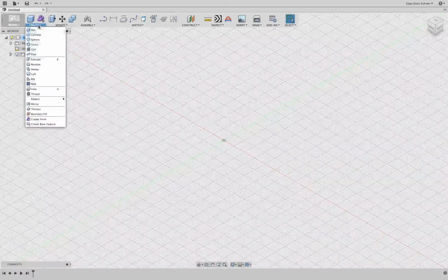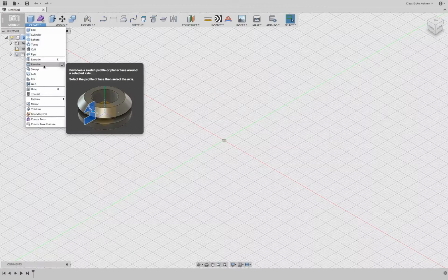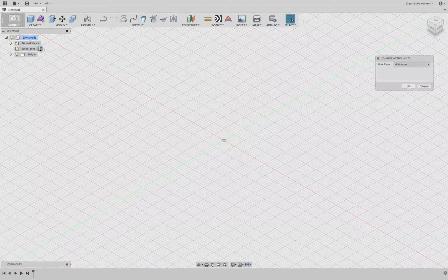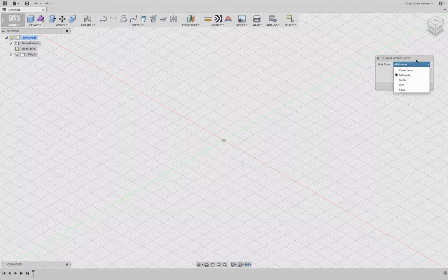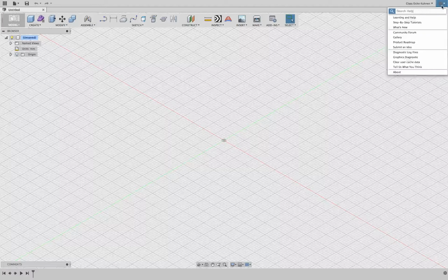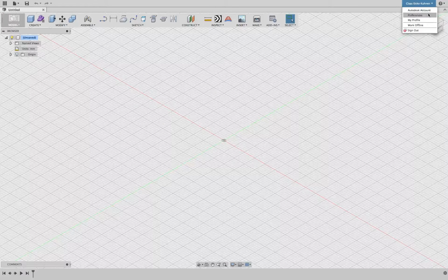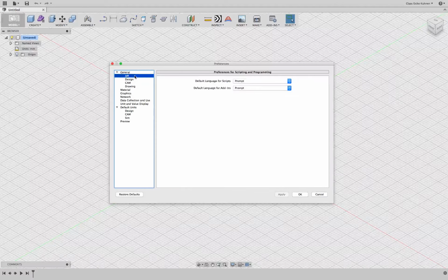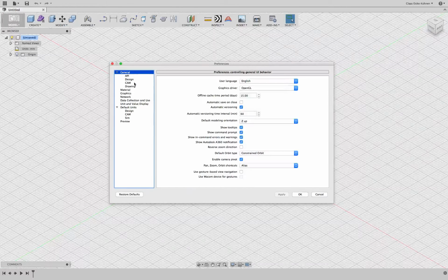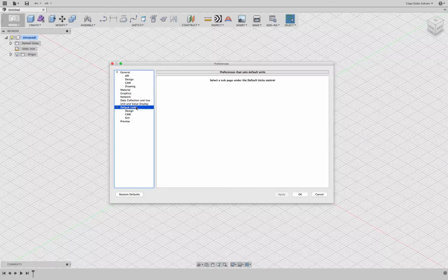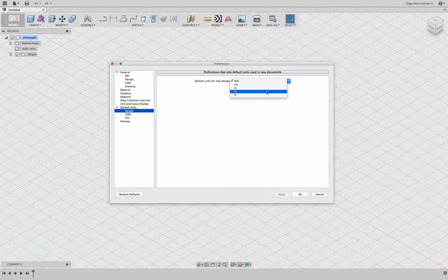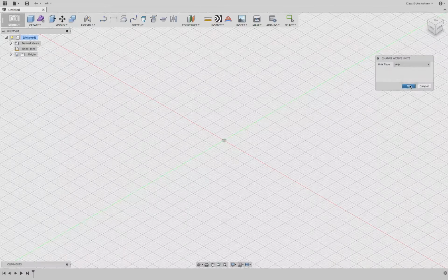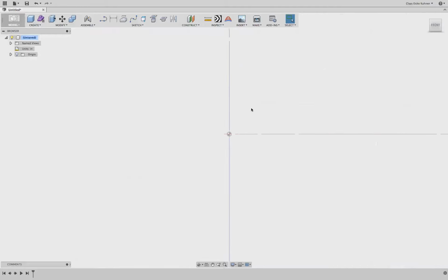Let's take a look at how we could use the revolve command to create something like a stool. So I will set my design to inches. Also, in case you want inches as your permanent measurement, you could go to preferences and, was it design? It is somewhere. Hold on, default units, there, design, and you simply set it to inches. Okay, so since I mainly work in metric, I will remain in millimeter and just switch to inches.